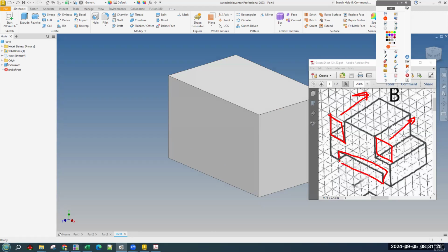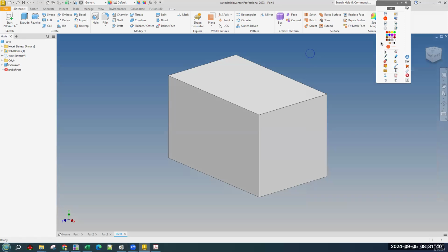and we can actually do all 3, this part, cut back, this part, cut back, and this part, cut back, all in the same extrusion. Looks like an angry face. And we can do that because the extrusion is the same for all of them. Obviously, the shapes are different, and there's actually going to be 3 different rectangles, but we'll do it all at once.